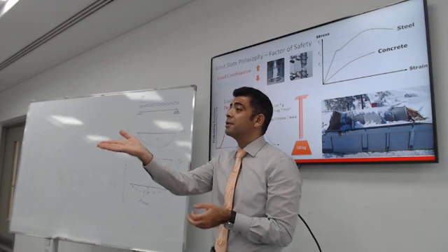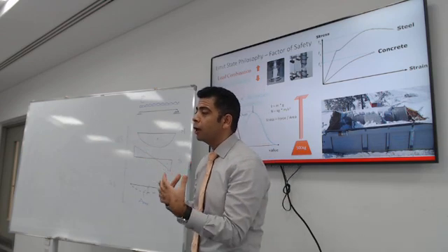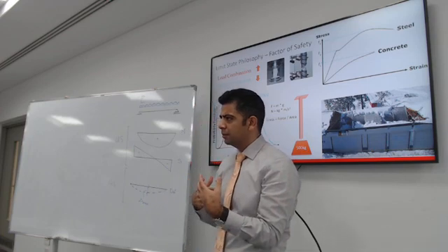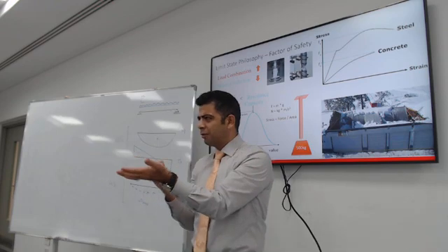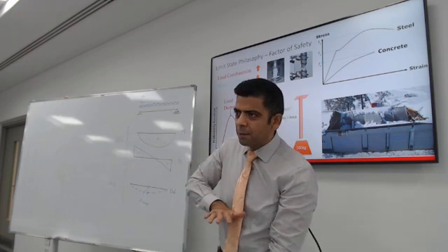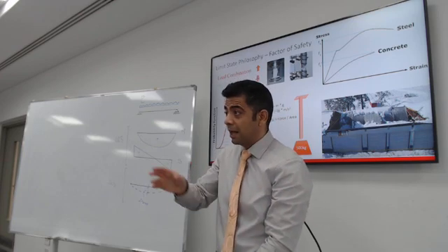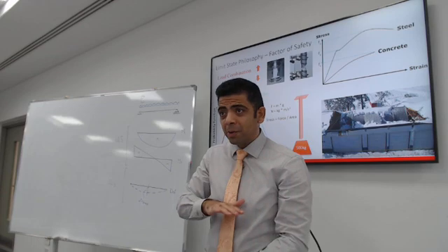You're designing a residential building using concrete. How strong do you want your concrete to be? I love that. C35. What is the 35? It's the maximum compression that it can take. It's an actual number. It's 35 MPa. The actual compression it can take.